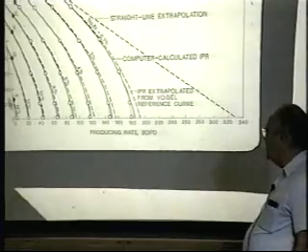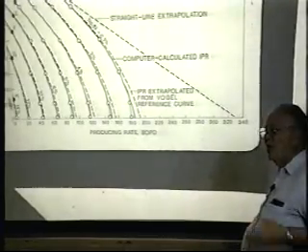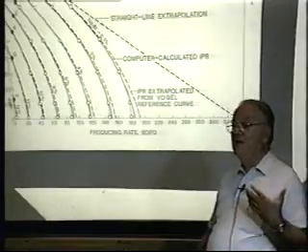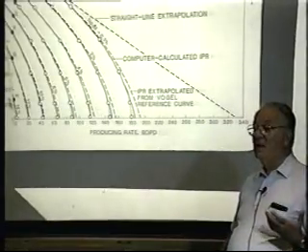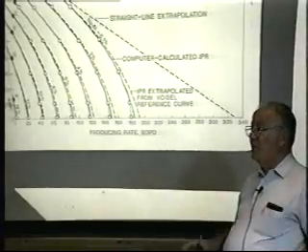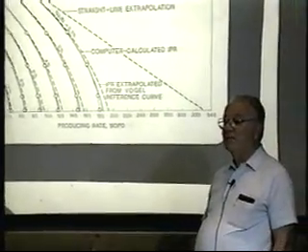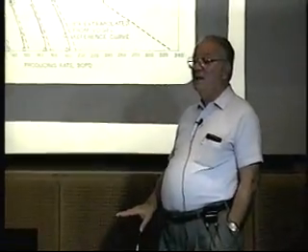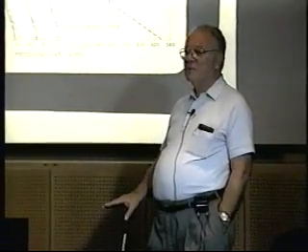When he presented it in dimensionless form, being in the gas department, we had a dimensionless form of the back pressure equation that we used to size orifice plates when we were running multipoint tests. And when I saw his paper, immediately it became apparent to me that what he's saying is that oil wells should behave just like gas wells. So I went out and got a bunch of data, including some on Ekofisk, and sure enough, when you plot the data up, it plots as a difference in pressure squared. As a back pressure curve plot, the shut-in pressure squared minus flowing pressure squared versus Q, it's a straight line on log-log.